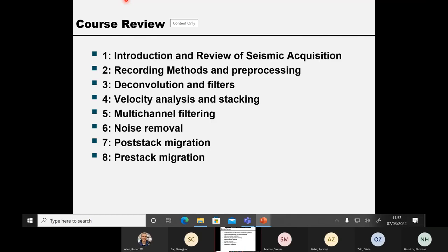Deconvolution and the filter, they are the same thing, but in a different domain. Deconvolution is based on superposition. The principle is superposition, and then we use Z transform. If you remember, I have the Z transform of one time series, and the Z transform of another time series. If we multiply the two Z transforms, we end up with another new Z transform. The coefficient is the convolution, right? So that also tells us that if we do a convolution in the time domain,